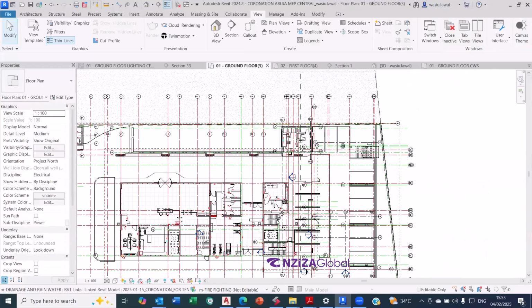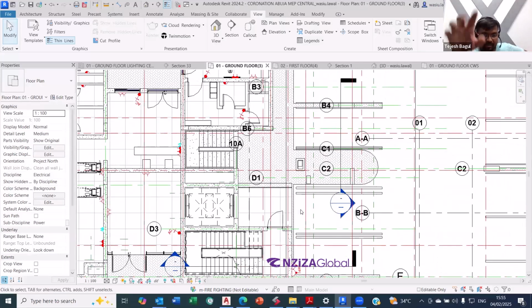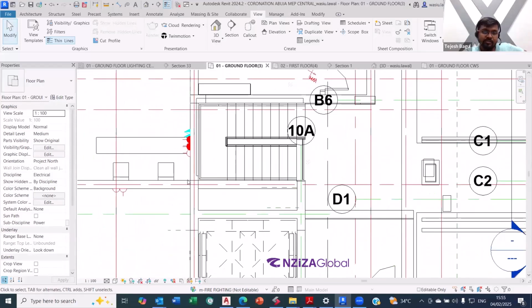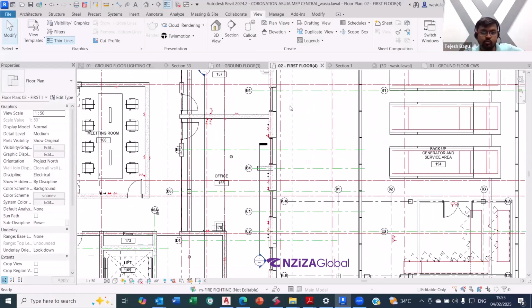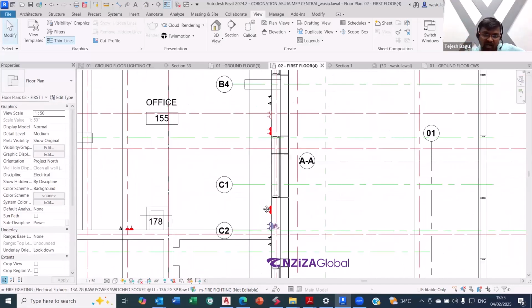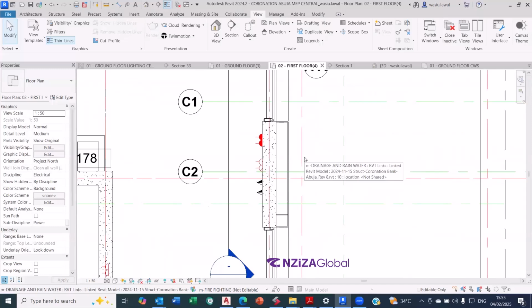Yes, it does. So either you can change your scale for this floor plan, but I understand what changing the scale means, or else you can ask your BIM manager, if there is one in your project, to change the symbols to make them smaller. Right now, the symbols are a bit bigger in the given family of Revit. Okay, all right. Thank you. Awesome.